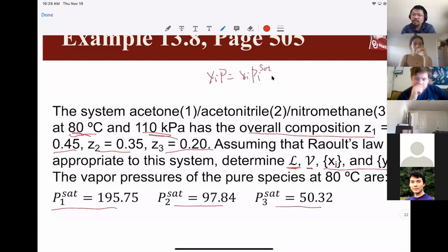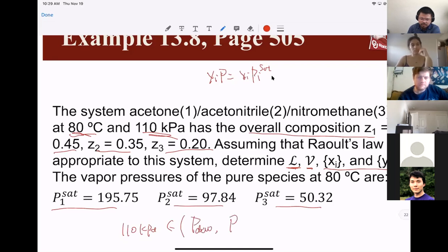Right. So I will not go into details, but when you read the textbook, you may feel a little bit lost. What's going on? How do we calculate the bubble pressure and dew pressure? First of all, we need to determine whether this known kPa is indeed between dew and bubble.